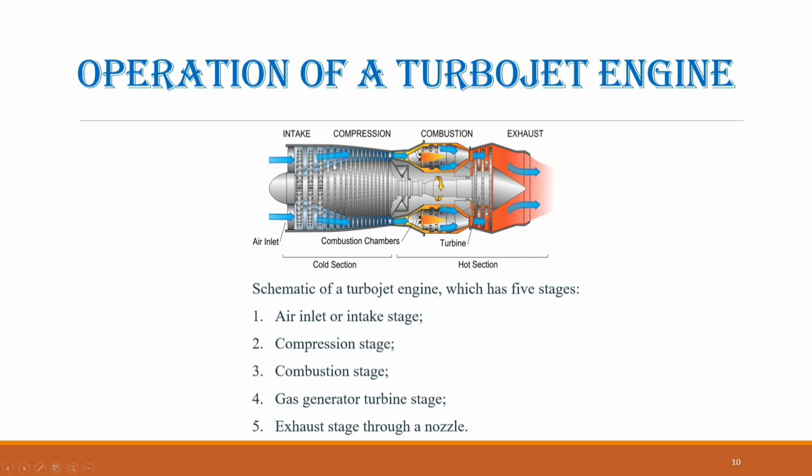2. Compressor stage. Once the air enters the compressor, it is directed over spinning blades and stationary vanes. Each stage of the compressor produces a small increase in air pressure, and successive stages result in a significantly higher overall pressure. Older turbojet engines used fixed vanes or stators before the moving rotor blades. Modern engines, however, employ stators with variable pitch to direct the airflow onto the compressor blades at optimal angles depending on the engine's speed and flight conditions.